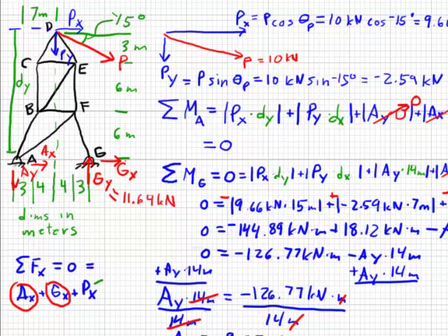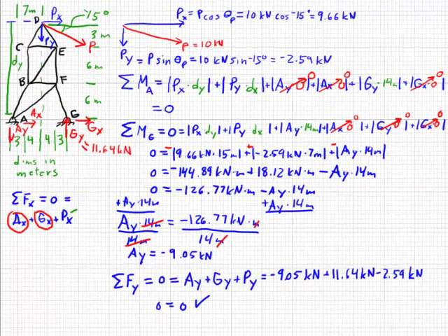If G had two struts coming off of it, this would be a statically indeterminate problem, and we would not be able to calculate this based on statics alone. But since it only has one strut, we can use the properties of struts to determine our Gx based on our Gy that we calculated before.